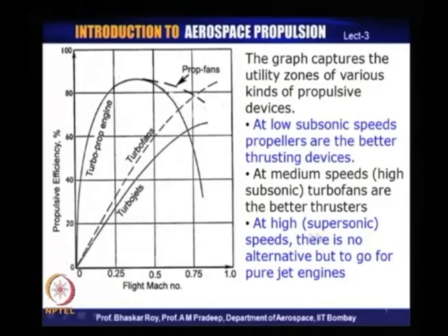In a supersonic aircraft, you need turbojets. So, when the Mach number of the flight is clearly more than 1 in supersonic aircraft, the choice often goes back to the turbojets or pure jets, in which you can get a substantial amount of thrust in a compact engine. However, let us remember, their propulsive efficiencies are never going to be very good.